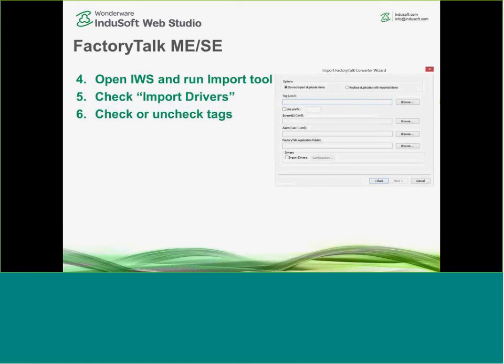Let's see, what else did I find? When I've gone through imports, one of the things that I found, and I don't know if this is necessarily true because I haven't used the latest version of this, was that if you fill out all of these fields before you click next, the tool didn't work as well as if you did the tags only and then clicked next and went through that, and then went back into the tool and did screens, and then did alarms, and then separately did the application folder.